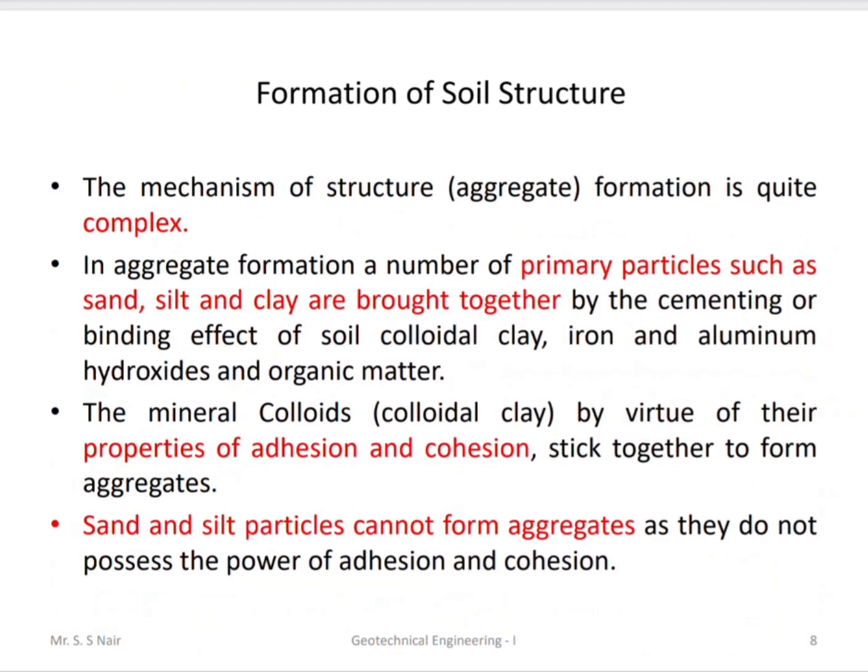Now the formation of soil structure. The mechanism of structure formation is quite complex. We also know the primary particles such as sand, silt and clay are brought together by the cementing or binding effect of soil colloidal clay, iron and aluminum hydroxide, and organic matter. Mineral colloids act by virtue of the properties of adhesion and cohesion.